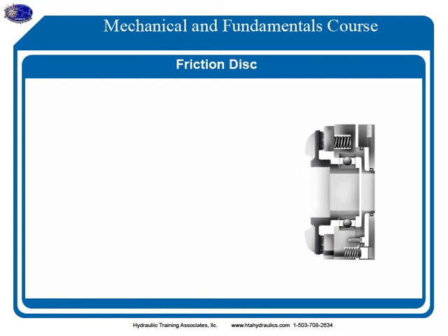Before selecting a brake, the resistance torque at the brake location must be determined. To determine the torque, you will need to know the motor horsepower, HP, and shaft speed at the torque location, RPM. The motor overload factor does not apply for brakes.